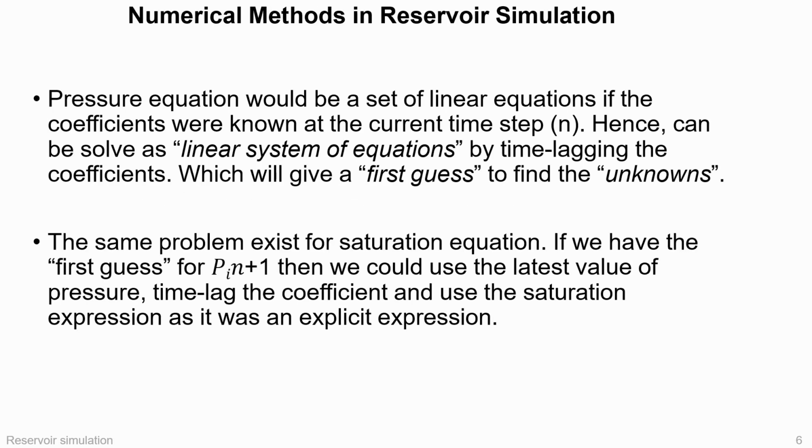This slide explains why pressure and saturation equations are not straightforward to solve. If all coefficients were already known at the current time step, the pressure equation could be solved as a linear system. But in practice, many coefficients depend on changing variables such as saturation and pressure themselves. That creates nonlinearity.